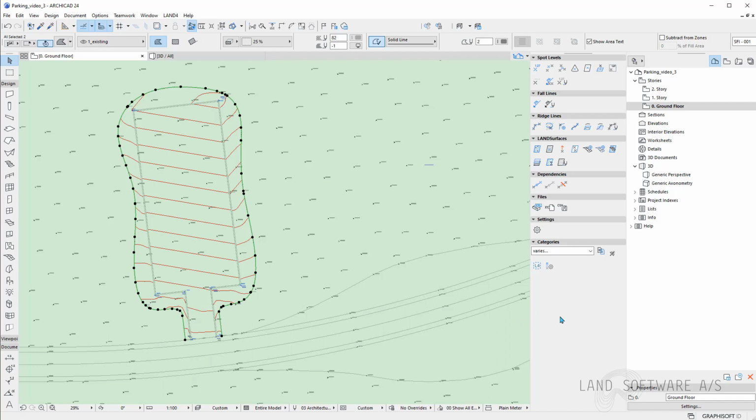Basically, a ridge slope is an interpolated line which is projected on the terrain based on a fall percentage in between the ridge line and the terrain. Once you press on the function button, you have your fall palette, and here you can add a different fall percentage. I'll start by maybe 20%.